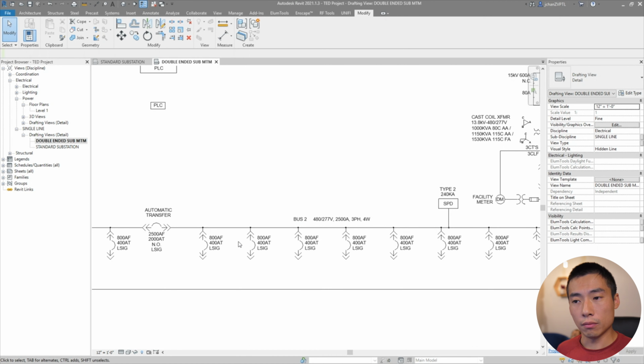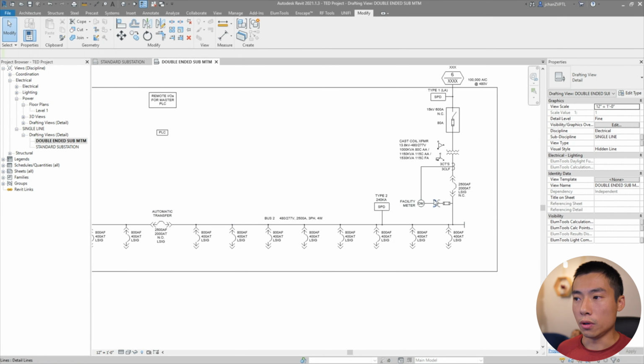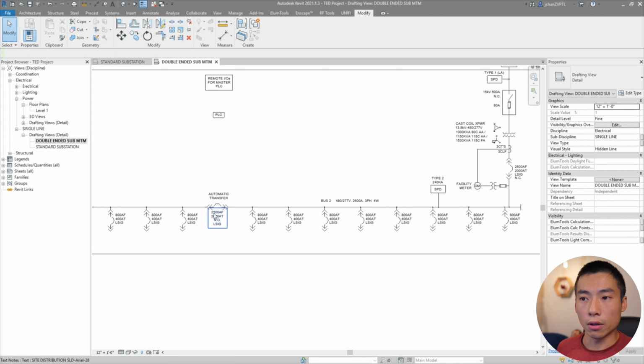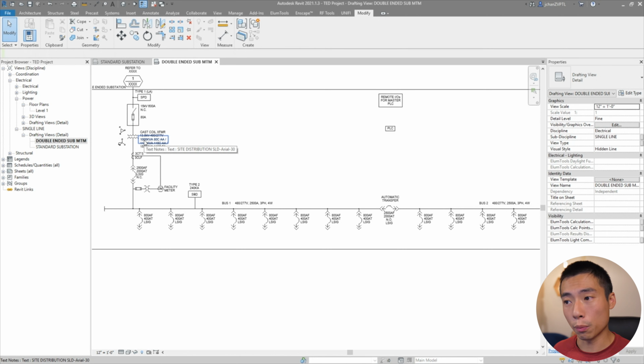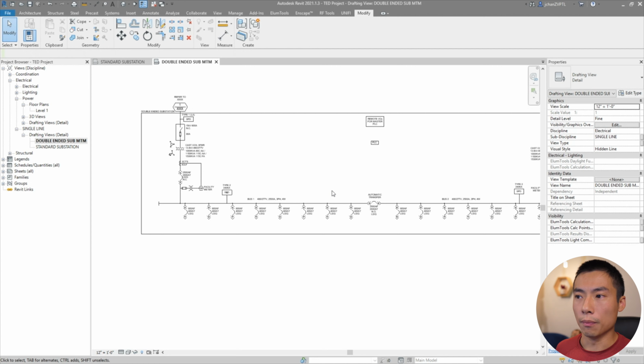Well, the system will now know that you can open this secondary breaker to disconnect side B because it's not useful to you, and close this tie breaker right here. So if you close the tie breaker, guess what? Bus A and bus B are now all together in one single bus. And that bus can be fed by this transformer. So this transformer obviously needs to be sized appropriately so that you can pick up the whole load.